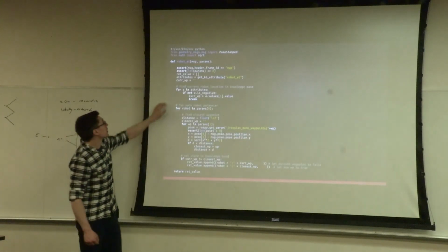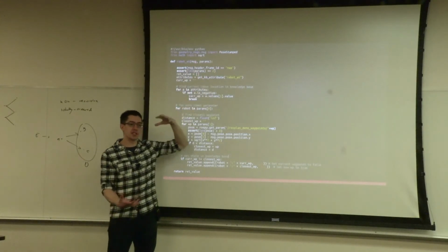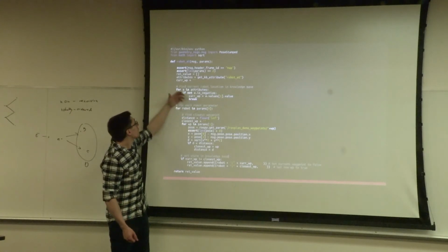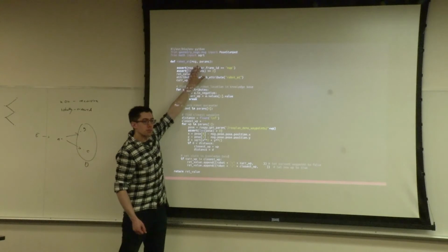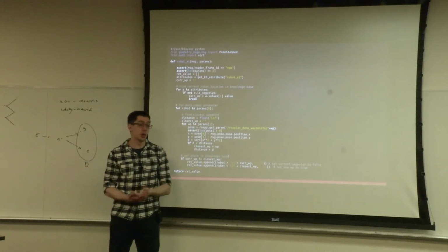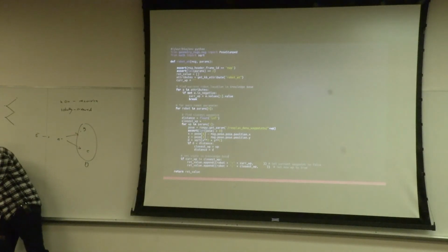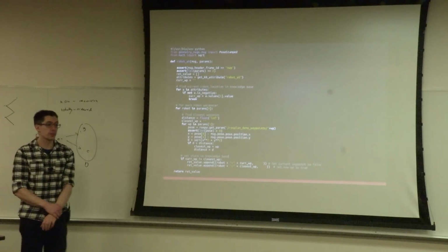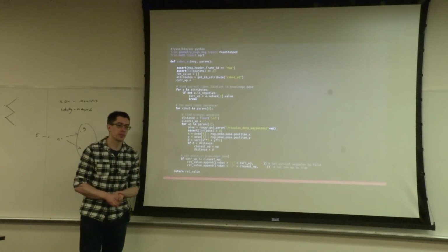So this Python file is importing geometry messages PoseStamped, which is that message type with the pose and the covariance and the timestamp, the frame ID. That message is being passed into this function, and this function is just checking what's the closest waypoint. So what I'm saying is, as soon as the closest waypoint is the goal waypoint for that action, that's before the robot actually gets there, it continues moving, it doesn't stop as soon as that's the closest waypoint.